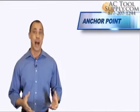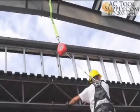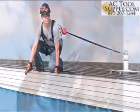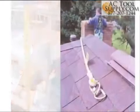An anchor point is a structural item such as an I-beam, scaffold, rebar, or lifeline to which workers are affixed when a fall hazard is present. It is sometimes referred to as a tie-off point. Anchor points must be carefully selected since workers depend upon their strength and stability in case of a fall.